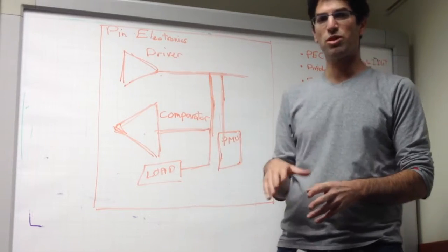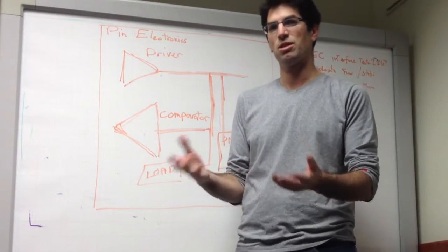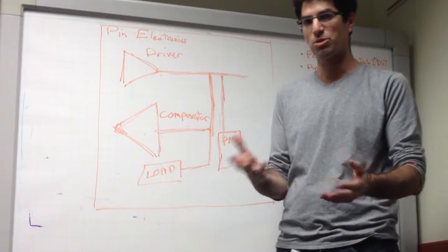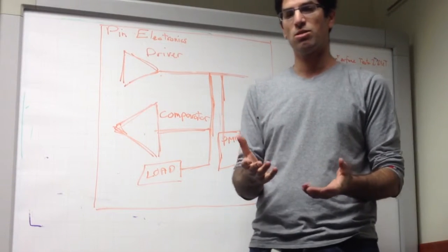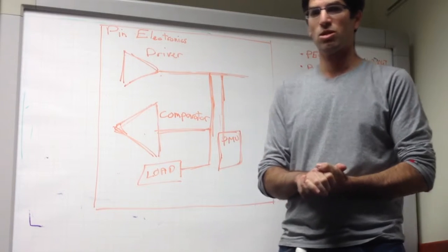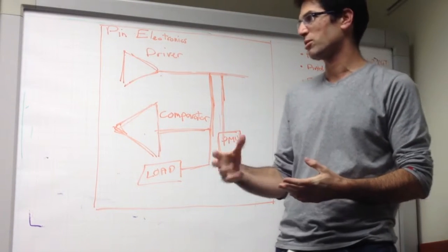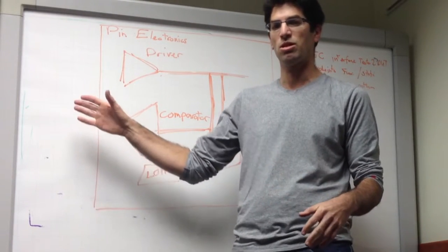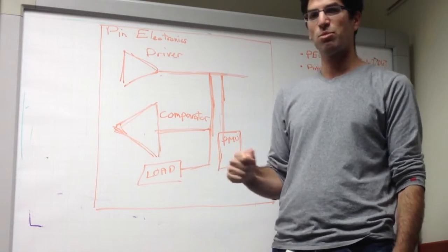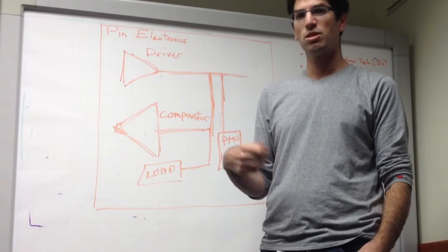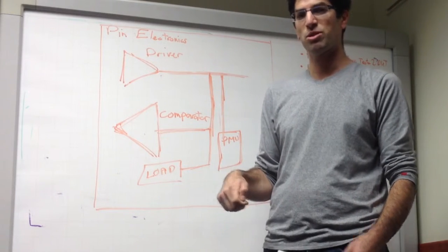The pin electronics provides the facilities to run both types of tests. So to run functional testing, we have a stimulus that is coded in the tester in the form of a pattern. The pattern can contain input pins and output pins.